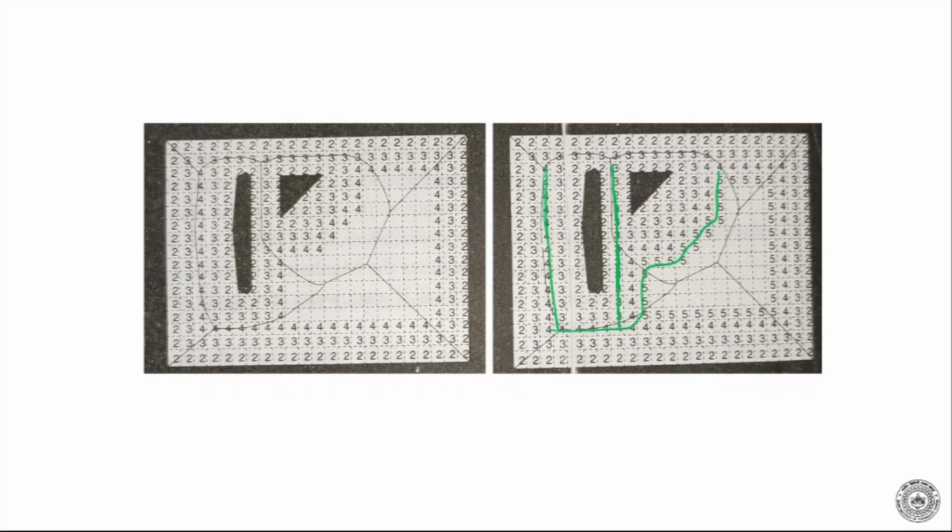Because wherever the number becomes highest, it can't go anymore. And it is going in both directions, from here and here. So the highest number is the one in the middle. So you basically have made your roadmap as shown here. This is your roadmap, which we have made in this grid format. Now you can start from the start point, join to the node, and from the goal point, you can join to the node and then follow the path.